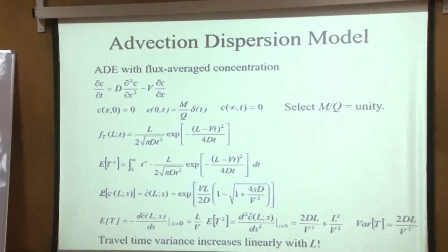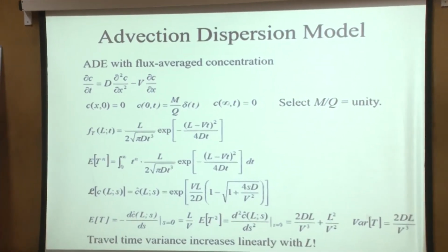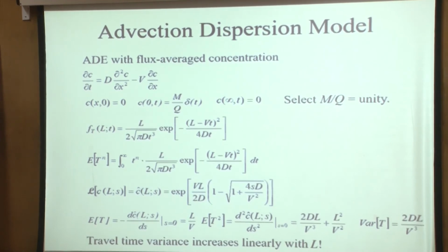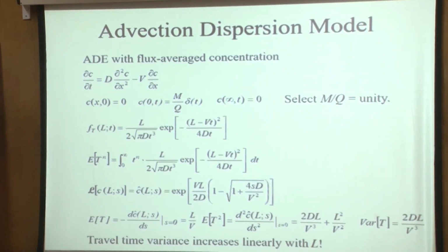Any guesses? Usually the simplest answer is the best one. In the advection dispersion equation, because it comes from the control volume analysis where we had space and time dimensions, L, or the distance in the column X, appears in the equation. If I fit a log normal distribution to the outflow curve, or a gamma distribution, how do I make it useful, for instance, for other distances if I want to know what the travel time PDF is?